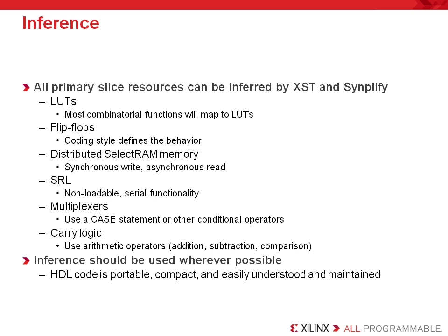Now, in general, inference is best and preferred by our customers. It assures portability to another technology and is reusable. However, most customers will have to do some instantiation to optimize the design for any FPGA on the market. So it's important for users to understand that there may be times when they have to instantiate the resource, or at least they're going to have to optimize their HDL code to get the most out of the FPGA.